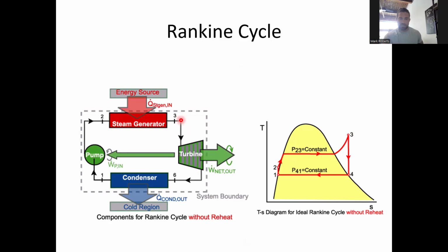And then when we send the superheated vapor through this turbine, which is high temperature, high pressure, assuming the turbine is 100% efficient, we have delta S equals 0. It's going to drop straight down. Now, if there's an efficiency, we could just move this line to the right based on what the efficiency is. We'll look at that later in an example.